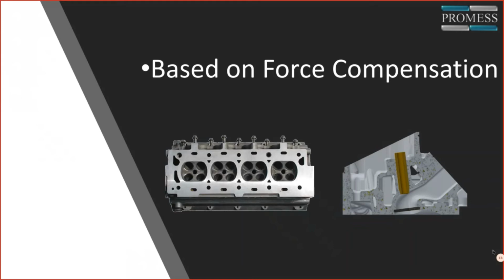And the higher the force, the greater the machine deflection. So what you can do is measure that force as you're installing the part and put a compensation factor in on the fly to compensate for any of the machine deflection.